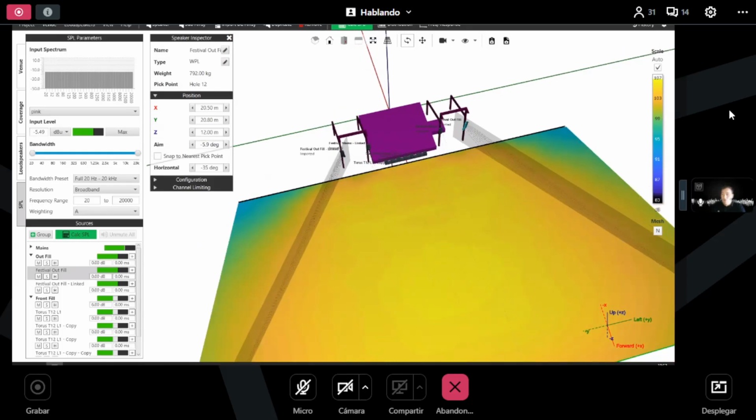So now all I ask is if you could create some screenshots using those tools, please. We would like broadband A, 20 hertz to 20K broadband A of the complete system, 500 hertz to 10K of the complete system, and then 4 kilohertz, 1 octave unweighted of the complete system. So let's do that.